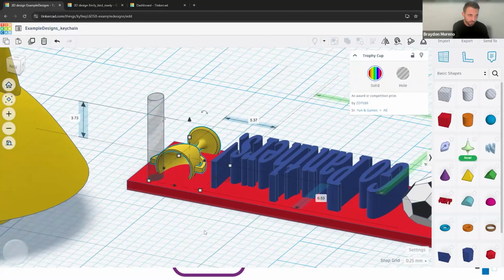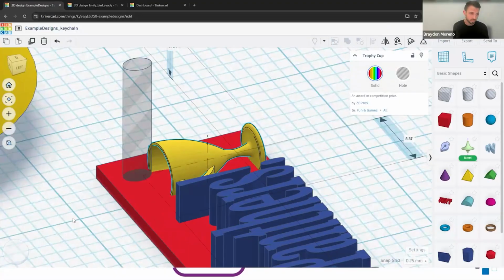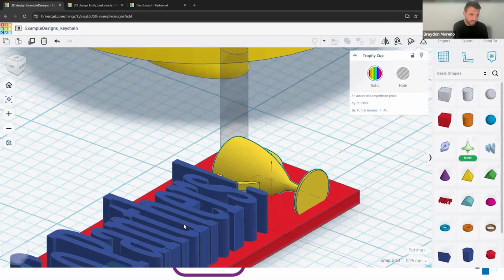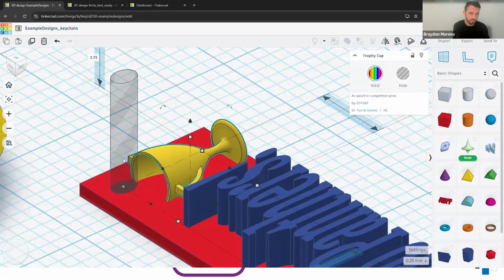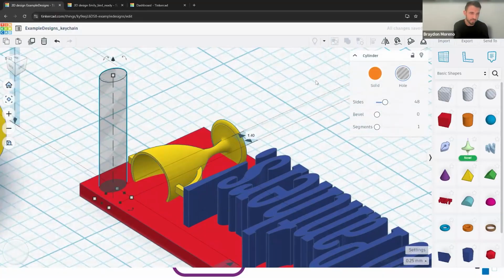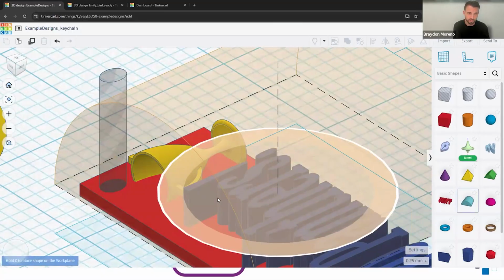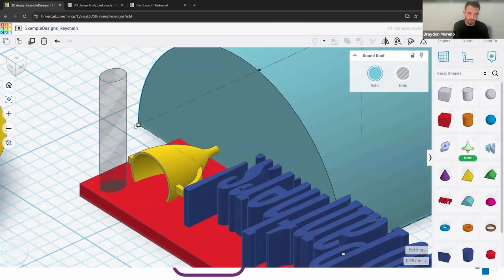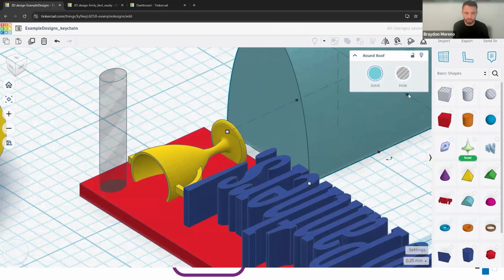Now, in the case of that yellow model, if you're unsure, because the print surface maybe is not super flat on the bottom or whatever it may be, you want to just turn supports on. We usually have them set to just auto add supports if needed. But if you're using any other printer or any other software, just add the supports if you don't know, because it will help ensure the success of the print.